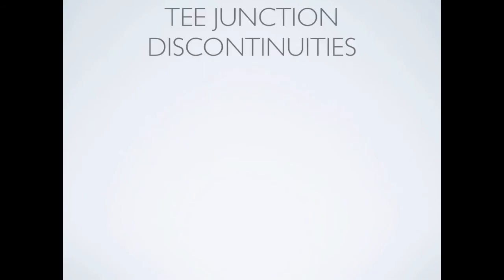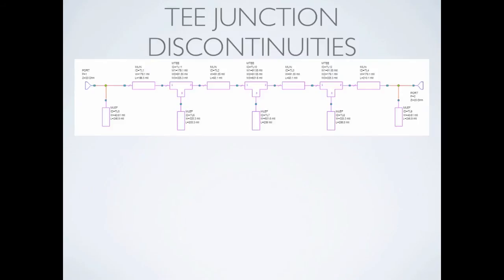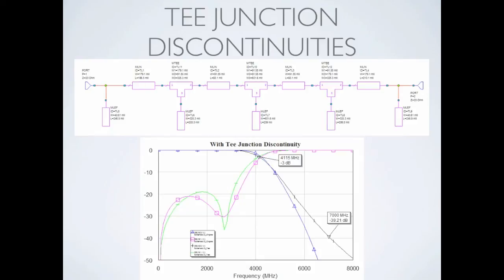However, when tuning the T-junctions, we decided to tune it the way we had done it in our last project, where we isolated and tuned the elements that made these junctions away from the main circuit. Apparently, this led to really bad cutoff frequencies and made our gain go haywire.